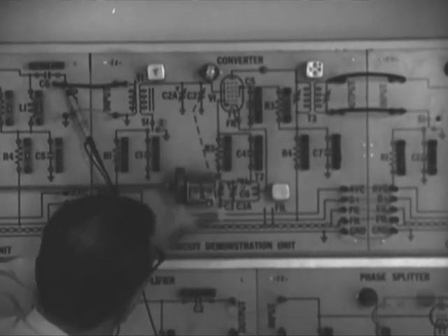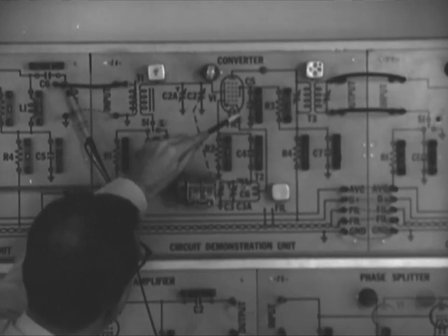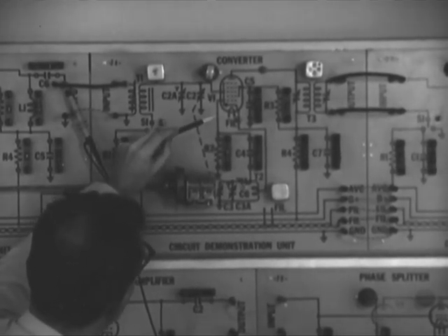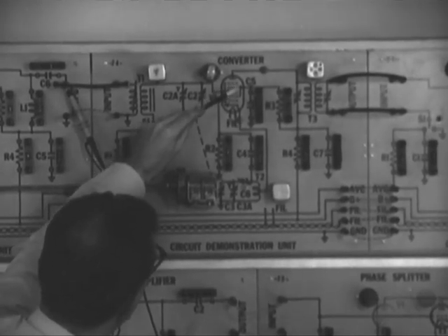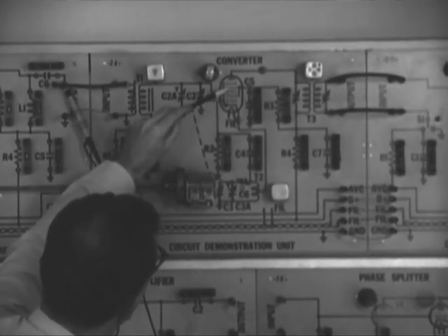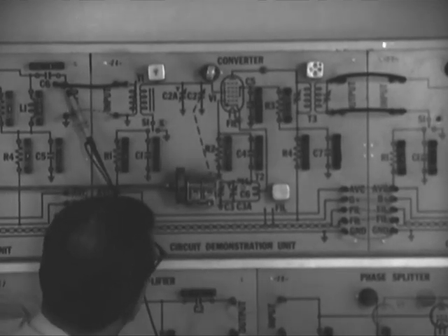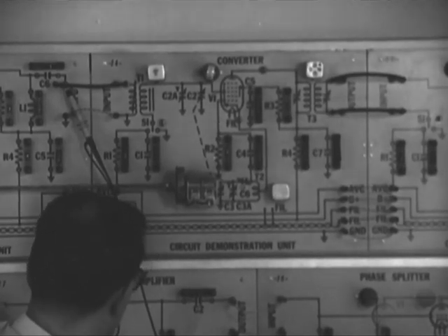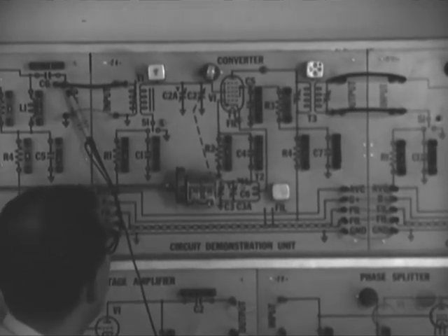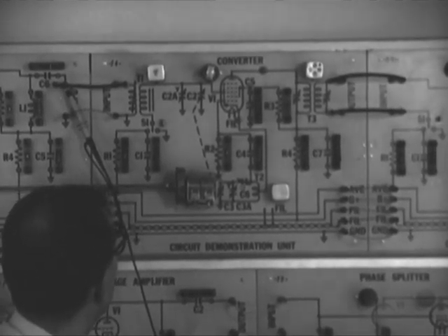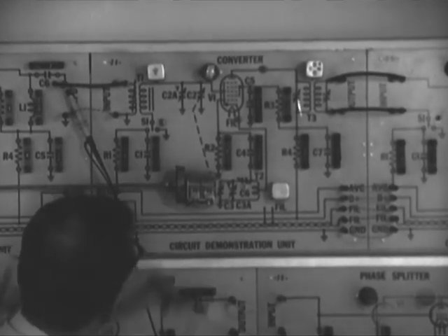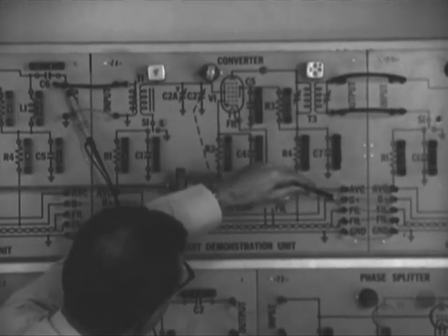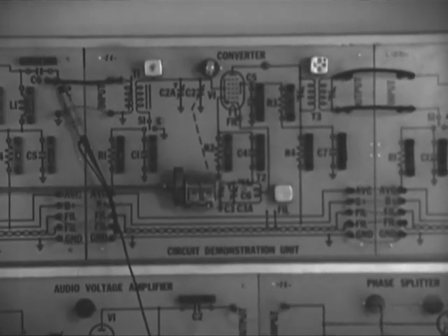In this circuit, the cathode and the first grid are connected in the normal manner, but grids number 2 and 4 are connected together and act as a plate for the oscillator circuit. These 2 grids are wound with heavy wire and have close spacing, so that a large proportion of the electrons strike the conductors. Positive voltage is connected to these grids just as if they were a normal plate. Those electrons which miss these grid wires are attracted by the positive voltage on the actual plate of the tube.